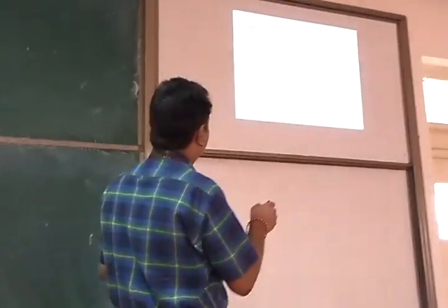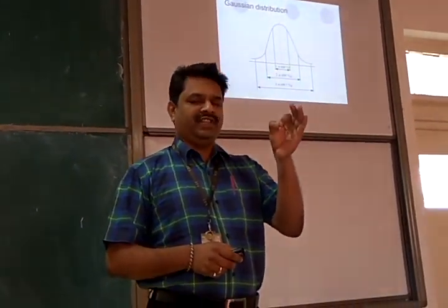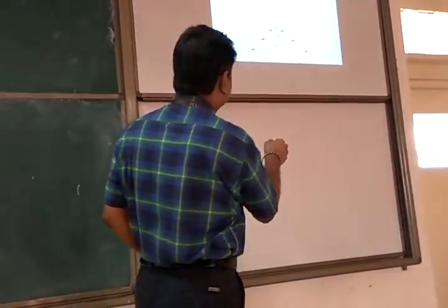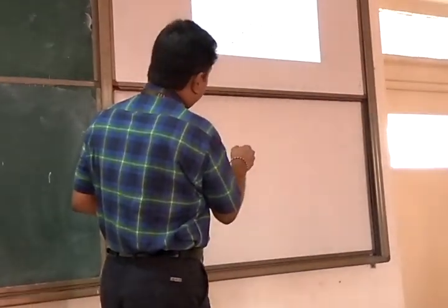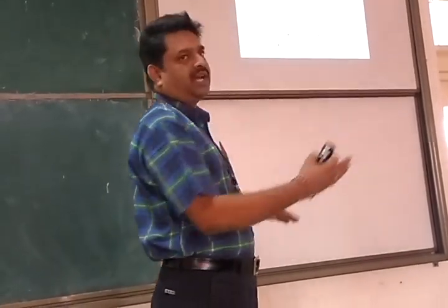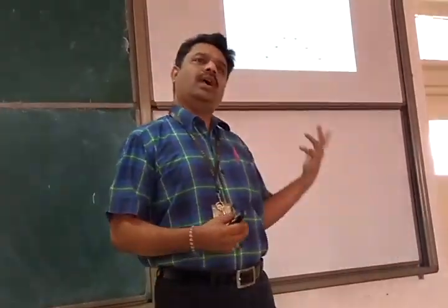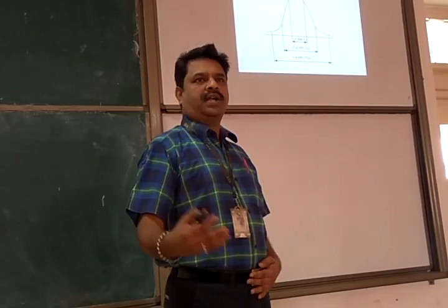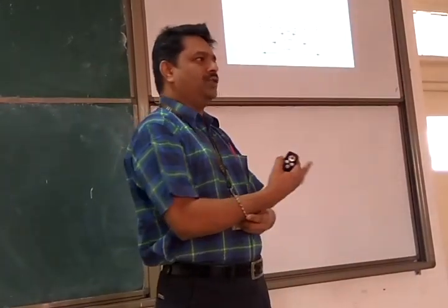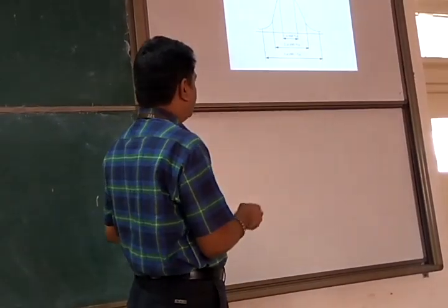For example, if the mean of the diameter is 50.651, around 50.651 you will have more values lying, and a little away from that it will be a little lesser. Maybe at the extreme values, either the lowermost or highermost, it will be less. So it will follow a Gaussian distribution, and then depending upon what type of stringent dimension accuracy your company follows, you will use 6 sigma, 3 sigma, 1 sigma, 2 sigma, all that you talk about. Sigma is the standard deviation.